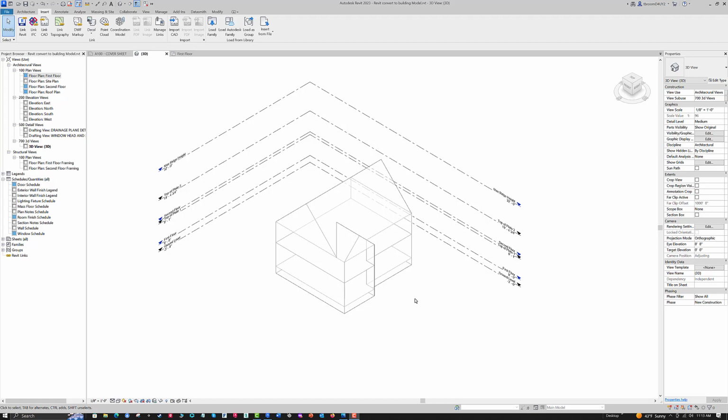In a previous video I showed you how to create a building shape using mass elements, and in this video I'm going to show you how to convert this mass element into an actual building using Revit's face tools. I'm also going to show you how to lay out a preliminary floor plan schematic using a tool that I created. Now we'll start by first converting our mass floors to floors, and then convert our faces to walls.